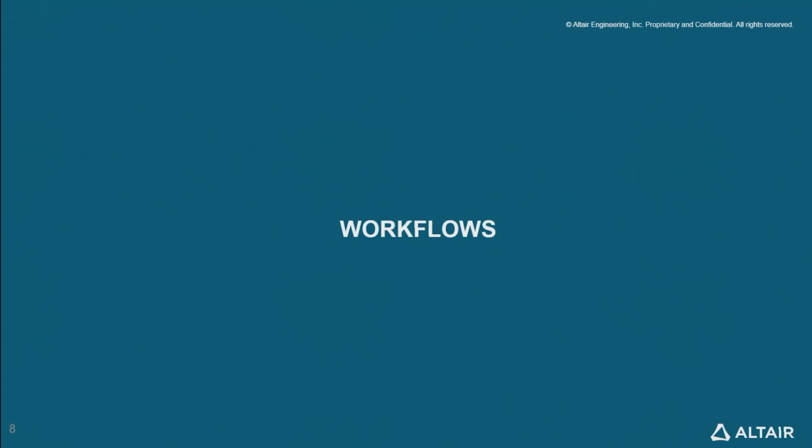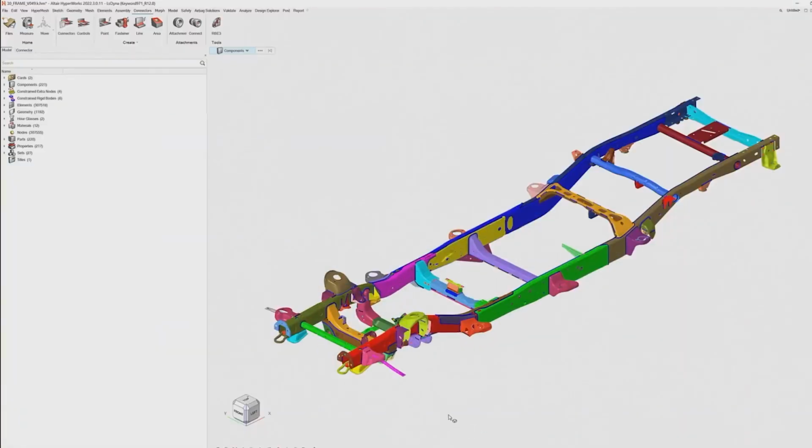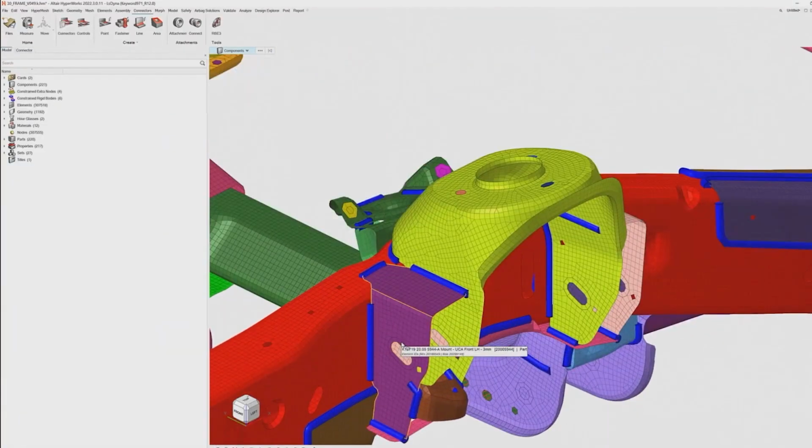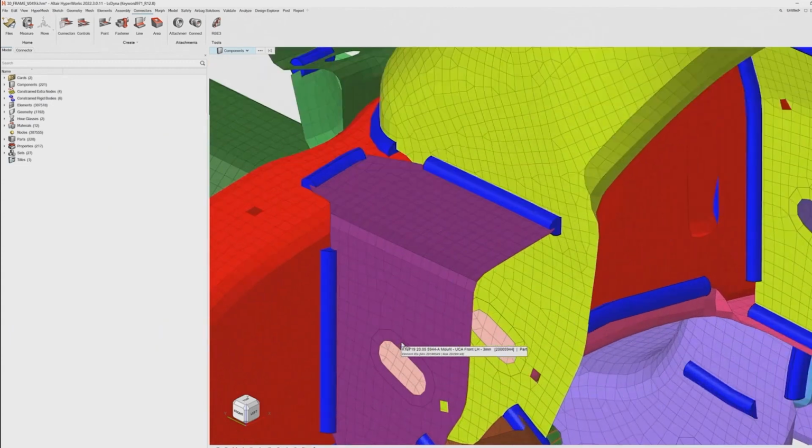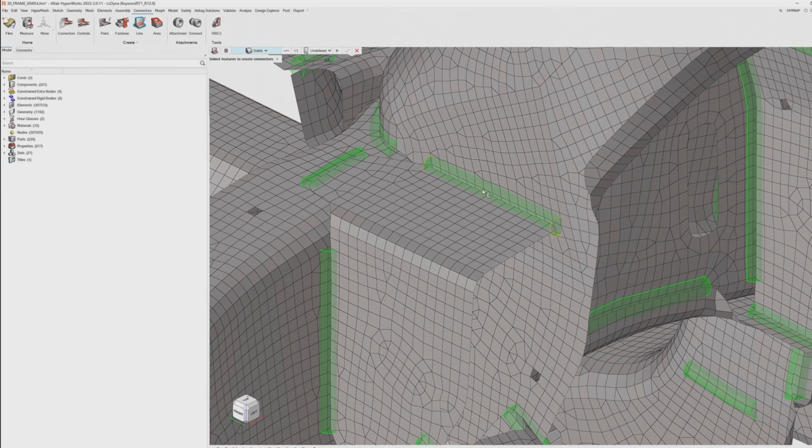What does that look like in practice? In this particular context, I've got some solid geometry representing a weld on a frame structure. I go into lines, I select my solids directly. That's not available in the old user interface, it's only available in the new user interface. My controls are automatically loaded, I select the realization style I'm going for, and I click realize. And that's it. That's now the only process required from a setup point of view.